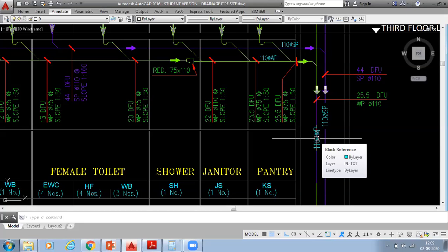So in our water supply, initially the pipe size will be higher. If you are supplying into a network, it will reduce based on the flow rate and the requirement. But in our drainage system, it is not like that. It will increase, the opposite. Small size to higher size will go for the drainage system because it is always carrying the load. So that's why it will increase.